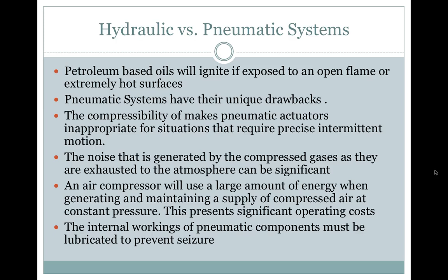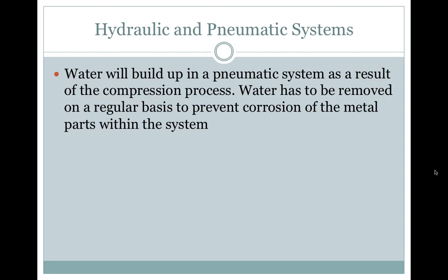The internal workings of pneumatic components must be lubricated to prevent seizure. Water will build up in a pneumatic system as a result of the compression process. Water has to be removed on a regular basis to prevent corrosion of the metal parts within the system.